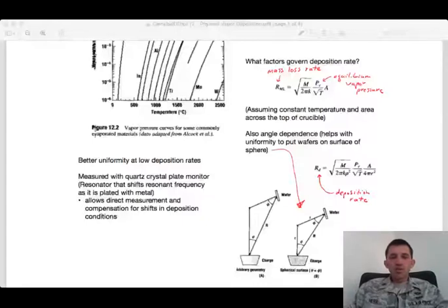And so you are using thermal energy to drive off these metal atoms from the charge, and when they're liberated from the surface, they have some thermal energy and they have a random direction. Since you've evacuated the chamber, they're just going to proceed in whatever direction they started at until they hit something, right?